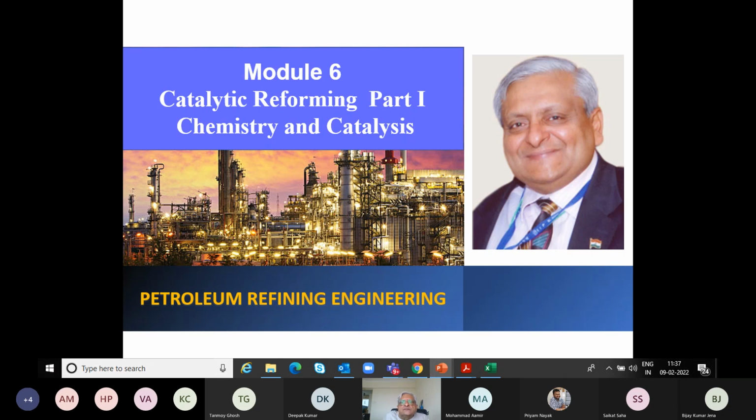And then from there, we came to the discussion on the crude unit, where based on distillation, or more precisely relative volatility, we were able to separate out the various fractions of the crude oil, all the way from fuel gas to LPG to light naphtha, heavy naphtha, kerosene, and vacuum. Some of these products are useful.